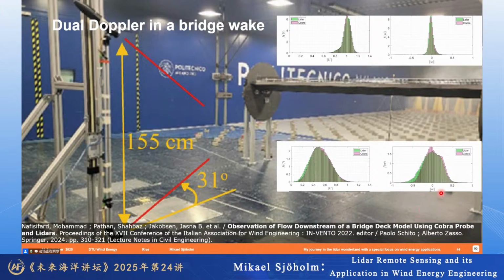Yeah, so this creates some opportunities to use measurements without introducing too much distortion due to point measurements. And it also requires less alignment and less backscattering than other optical techniques, typically like PIV and laser Doppler anemometry in wind tunnels.